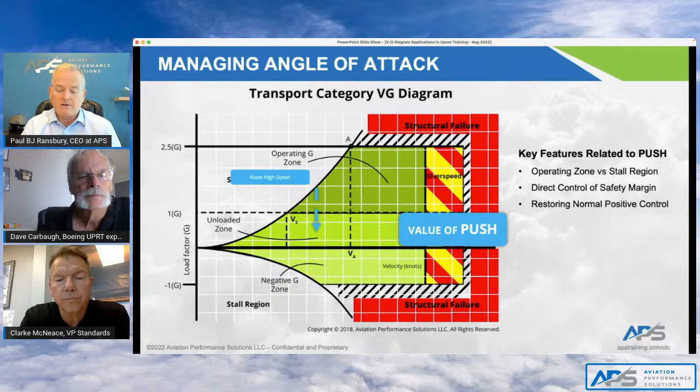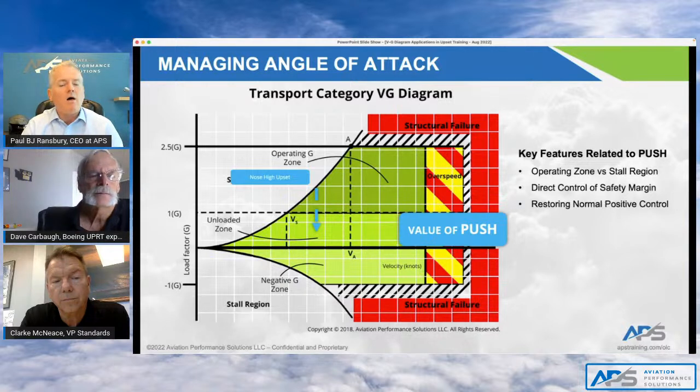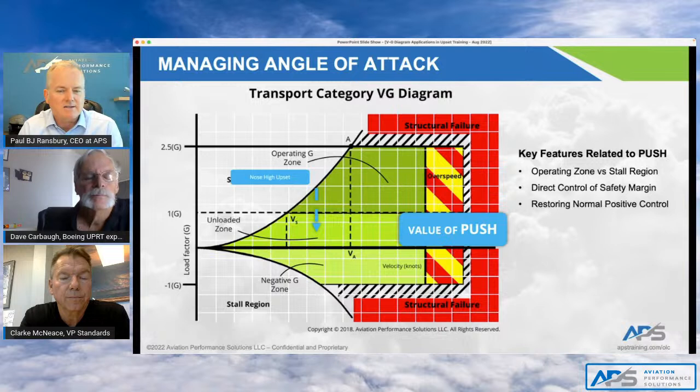Absolutely, and it's starting to counter the push, right? In smaller airplanes, the thing to remember is that very often pilots think that in a nose high upset, speed deterioration is the number one threat. While that is true in one sense, remember that airspeed in a nose high upset event really just helps you control the airplane, assuming that your angle of attack is below critical. It maintains energy and controllability, but what's really keeping you safe is the unload or reduction of angle of attack to take advantage of that energy, depending on the situation, like Dave talked about, to maintain controllability. Otter, anything to add there at all?